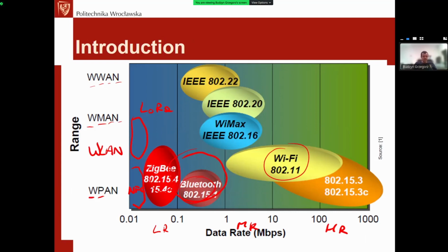We will start, but not today because it's almost a break. I will try to show you the options we have from a microcontroller's point of view, especially the options that we have already included as peripherals, because we can always use modules. So 4G, 5G, Wi-Fi 802.11 is a fantastic option delivering hundreds of megabits per second theoretically, but it's not present in any microcontroller to my knowledge.